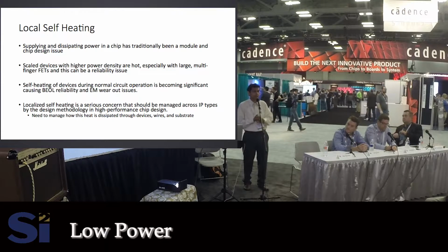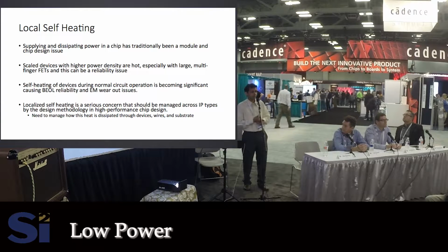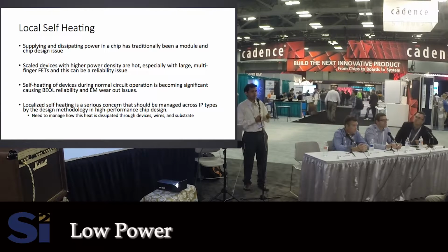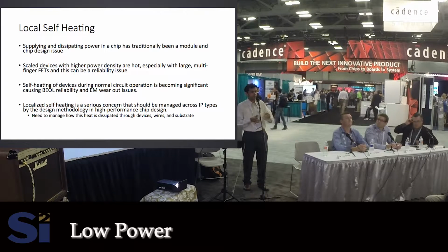So it is a concern, and it's not just the traditional approach of, at the very last minute, your circuit designer trying to simulate with the circuit simulator to get the self-heating impact. That really is not enough. That's still needed for very accurate sign-off, but if you can manage this early on, while the macro is being constructed, being able to assess these impacts early on is significant.